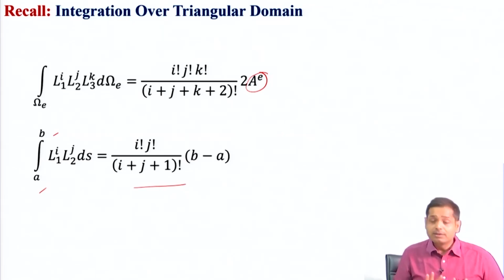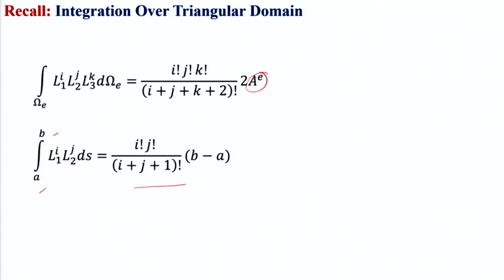So with this, let us stop here today. We now know how to construct the shape function for a triangular element, a higher order triangular element. We have derived the shape function in terms of area coordinates for the linear strain triangle, but we know the procedure. So applying the procedure, we can get the shape function for other higher order triangles as well.